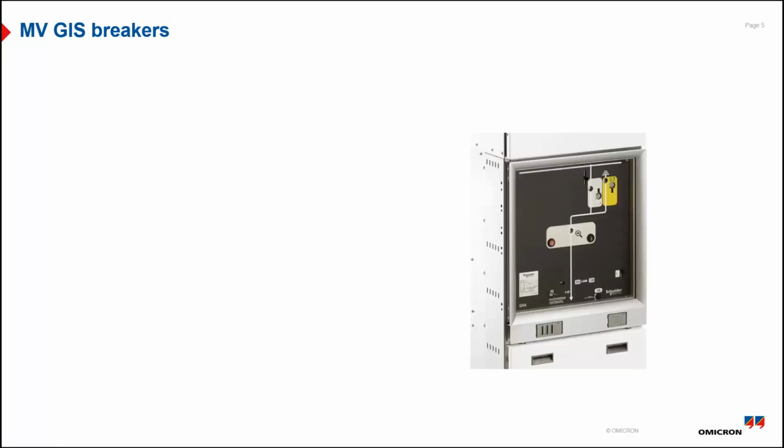Now, a few things for us to note for these types of breakers. If you look closely at the control panel of this GHA type of breaker from Schneider, the whole primary circuit is sealed off, as I mentioned earlier. So there is no way to access the main contacts physically.